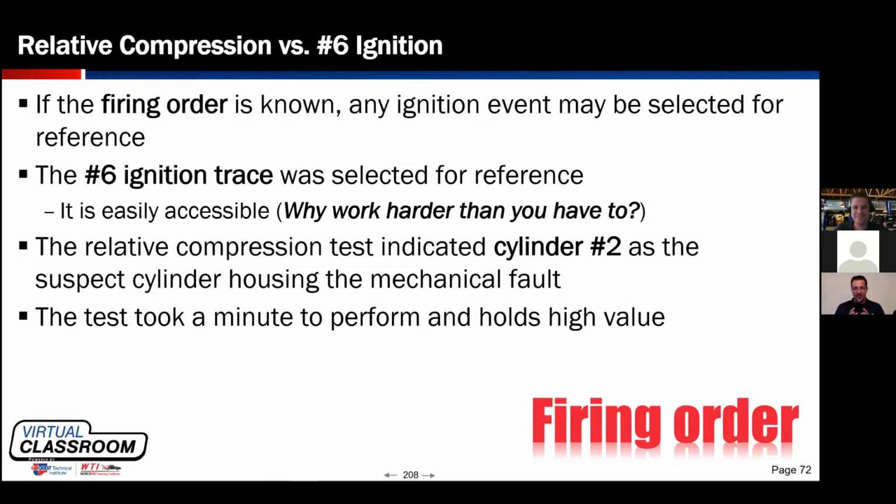Okay. Now, think about it like this. The relative compression test states cylinder number 2 is my dead hole. For whatever reason it is, that cylinder cannot load the starter. Don't I have enough evidence right now to pull the number 2 spark plug out and go in cylinder? I do, don't I? If I was doing this for real now, I might go directly in cylinder, right?